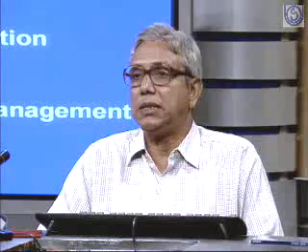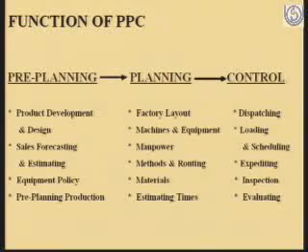At that time problem crops up. And when a problem crops up at a later stage, rectification of the product is more costly than if it is corrected at the design level. And that's why today, whenever the question of product development and design comes, everybody tries to design by considering DFM, design for manufacturability, that the viewpoint of the manufacturing department needs to be considered at the design stage itself.